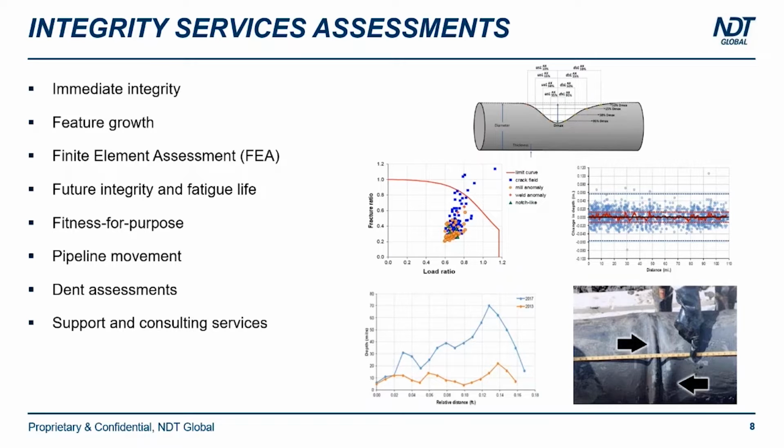So standard methodologies follow ASME B31.8 2018, considering only the deepest point of the deformation. Knowing that we have an ultrasonic geometry tool, we can also follow the same approach of B31.8, but considering a point-wise calculation of the longitudinal membrane, leveraging this high-resolution ultrasonic data. So we try to ensure that all the data is being used and enhanced for these assessments, not only providing the assessment as written.